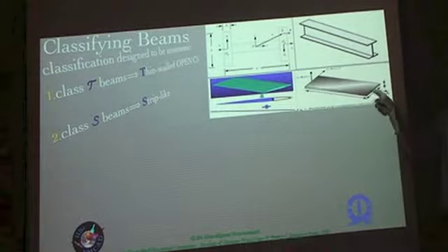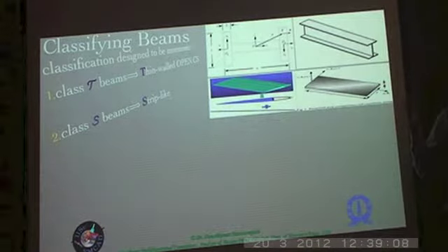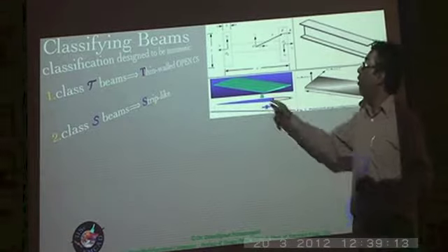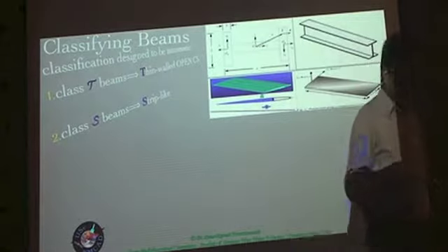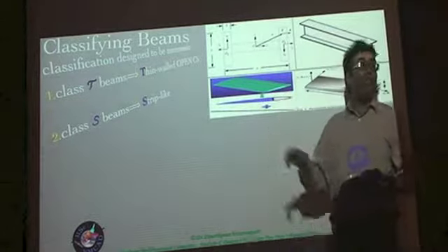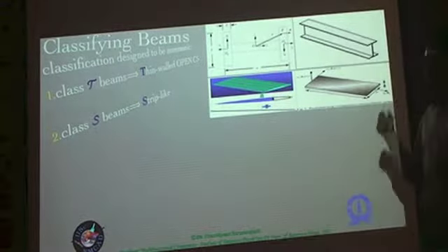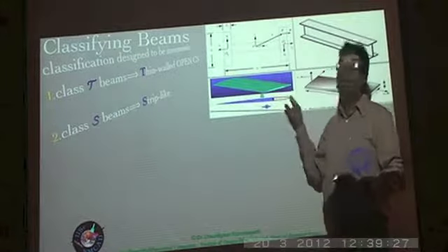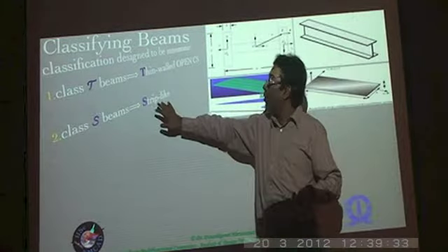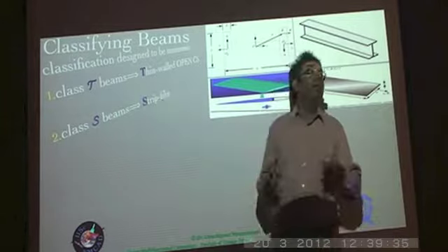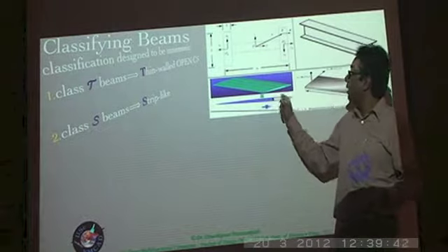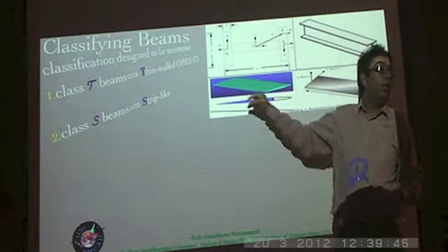So of course it involves the thin rectangular strip that we have been often talking about as an interface between open sections and closed cross sections, but it can also involve airfoil-like cross sections, especially because many airfoils are thin, especially for higher speed aircraft, and the thickness to chord ratio is of the order of 10% or lesser. So basically the h by b is a small parameter. So even for airfoil-like cross sections, the more appropriate classification would be strip-like beams rather than a solid cross-section beam, irrespective of how the material itself is distributed within that particular geometry.